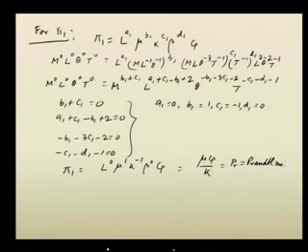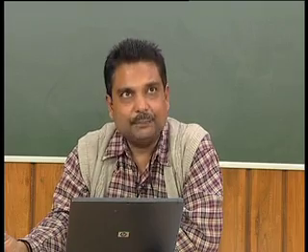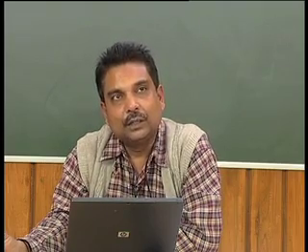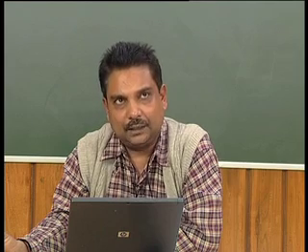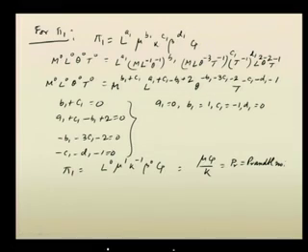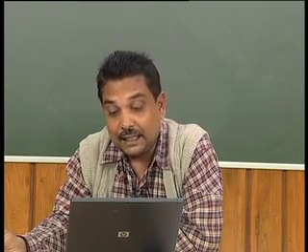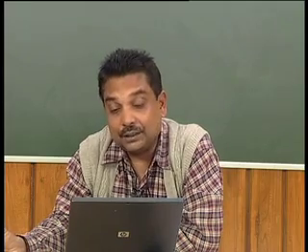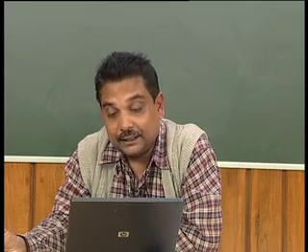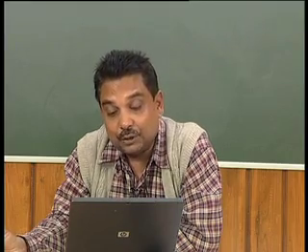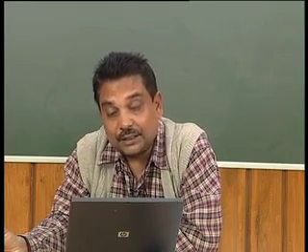Whenever heat transfer phenomena and fluid flow are involved, the Prandtl number is an important parameter, because it takes care of momentum transport as well as energy transport. It is a ratio of two diffusivities, momentum diffusivity to thermal diffusivity, both of which are happening. In laminar flow, it is a molecular level phenomenon, and in turbulent flow, it is assumed to be like eddy movements. In laminar flow, it is the movement of molecules that carries the momentum transport as well as the thermal transport.